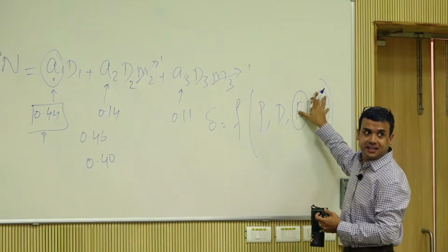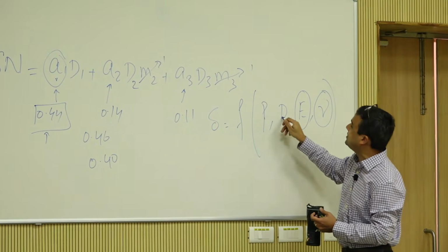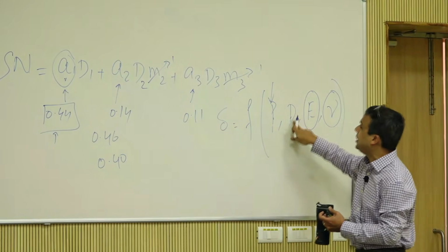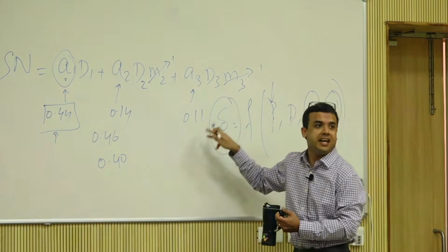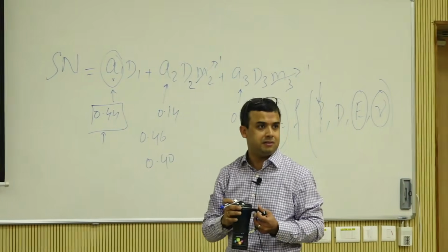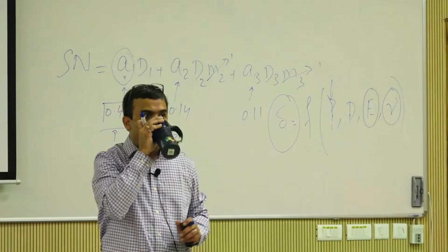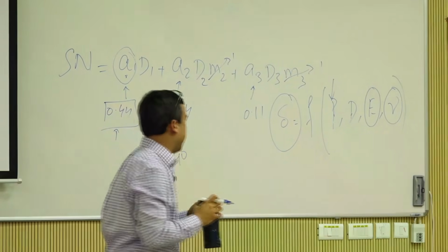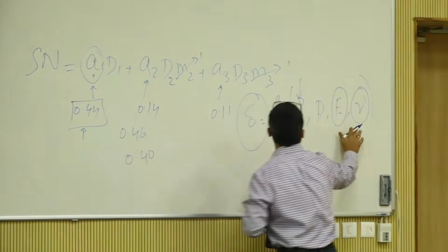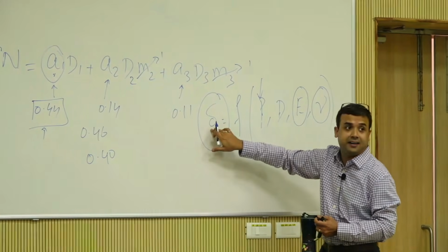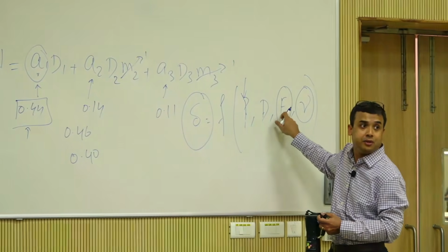So you determine these and then you do this and this. This is known already, this is the demand. The D is what you determine so that your delta is in a stable range. This is forward calculation right now: delta is equal to this function. So if you have an existing pavement and you are measuring delta, then it becomes back calculation to determine E.